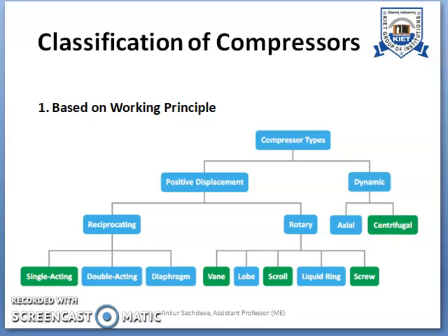Okay. Now similar to that case, the positive displacement compressors are those in which the refrigerant vapors are physically displaced by the moving part of the compressor, that is the piston displacing the physical boundary of the fluid. Whereas in case of the dynamic kind of the compressor, we have the action taking place between the moving blade and the fluid, that is the blade imparting the energy to the fluid in compressor.